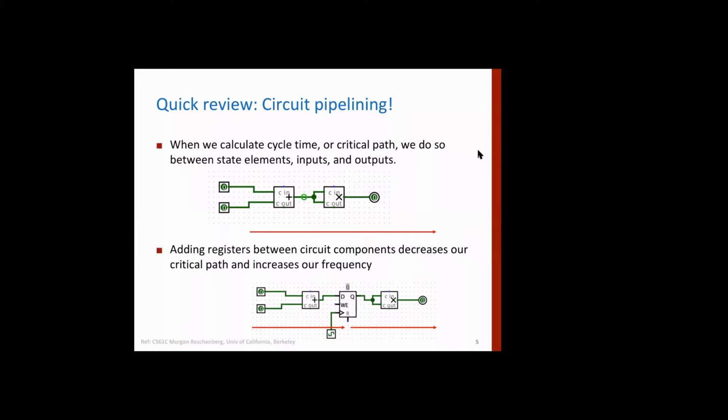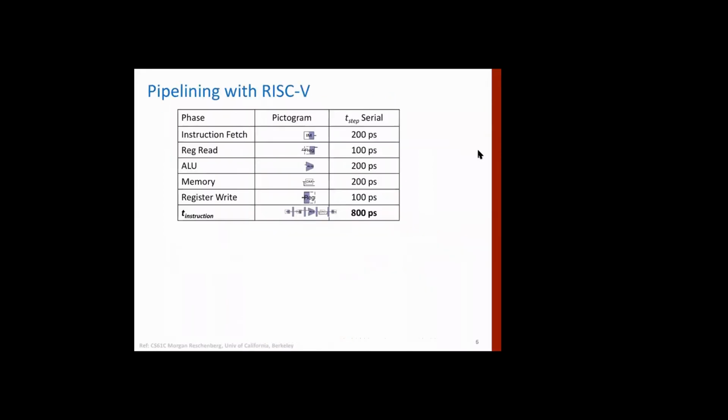So in order to do that, we put some registers in between. For example, here we have put in a register, so this becomes one part, this becomes another part. Whatever is here needs to be done within a clock cycle. So if this is not much, then we can increase the clock speed. That's the concept, right? And then we have seen this way of representation of the instruction, which we are going to use in subsequent slides, right?